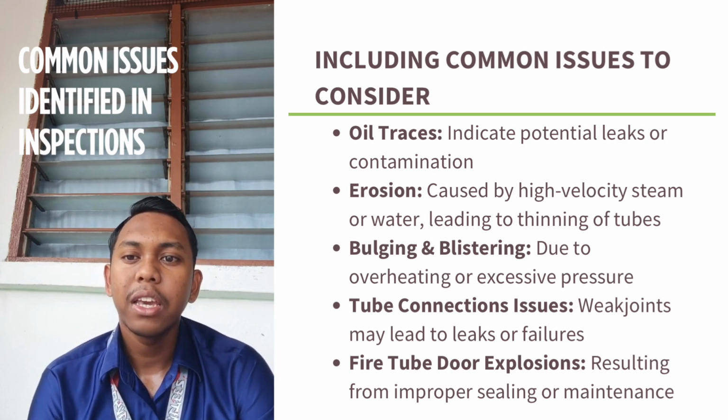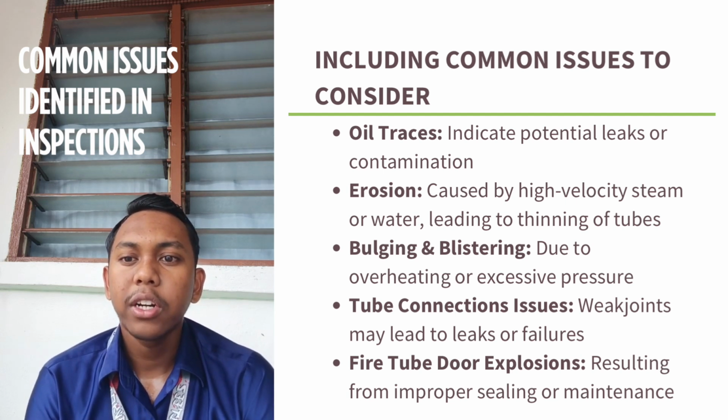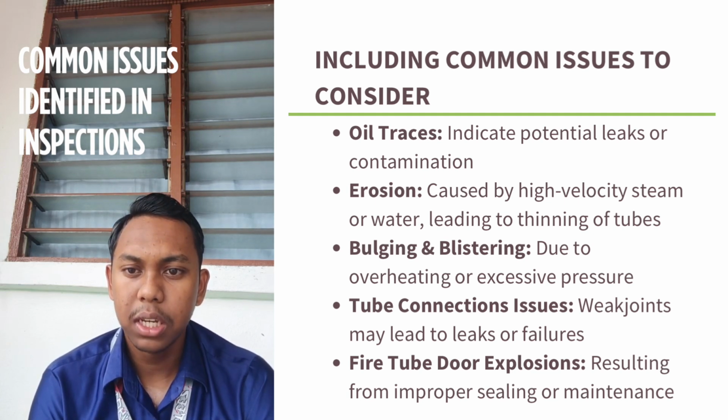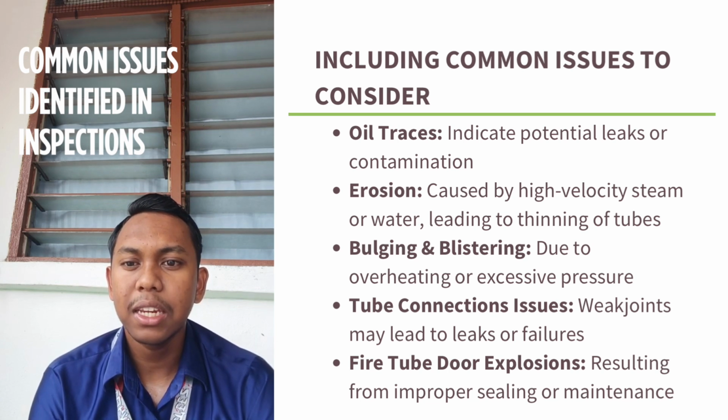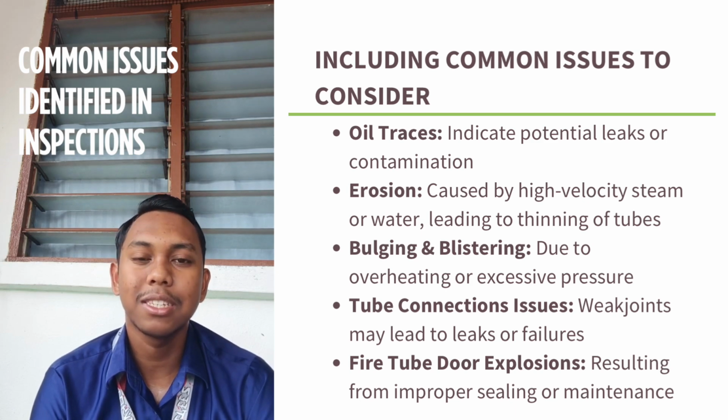Lastly, fire tube door explosion. It occurs when the fire tube door is not properly sealed or when combustion gases leak. Gas buildup can ignite, leading to small explosions that damage the system.